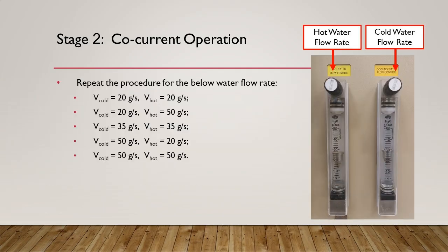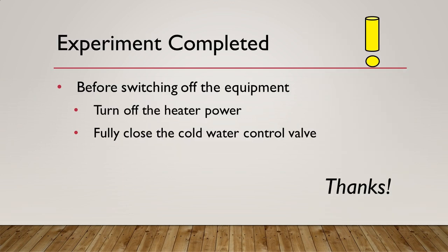Again, set the cold water flow rate and hot water flow rate as shown below, and record the water temperatures. The experiment is completed. Before switching off the equipment, please turn off the heater and fully close the cold water flow control valve.